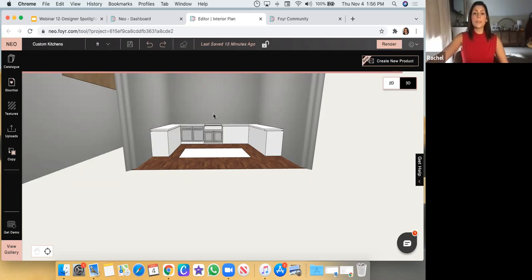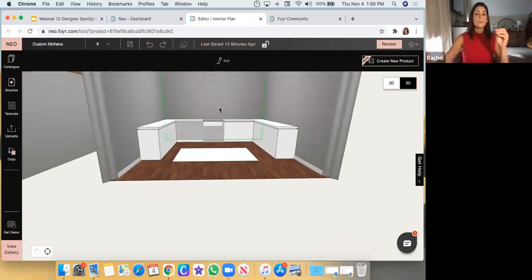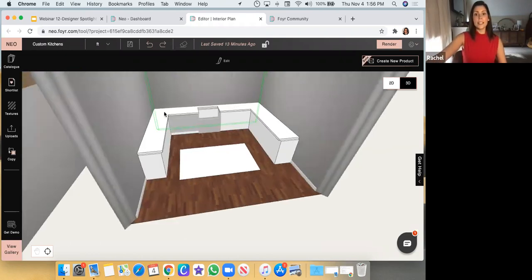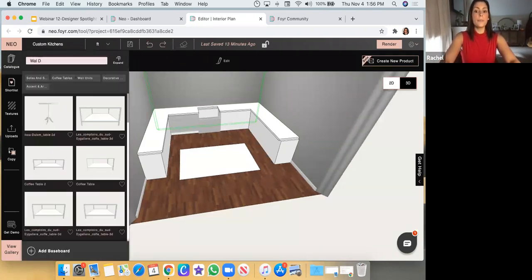But say it's subway tile where you want that grout to be lining up on this side and this side. If you clone this wall docked cube that you've just dragged and dropped and then rotate it onto this wall, keep in mind that if this length here is very different from this length here, if you edit the texture size or the number of tiles on this wall, it's going to affect this one as well. So depending on, let me just show you an example of that.